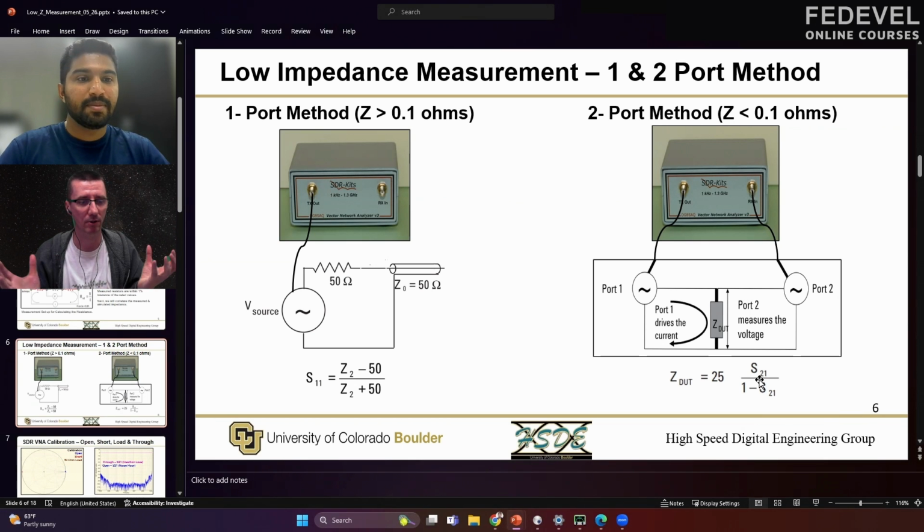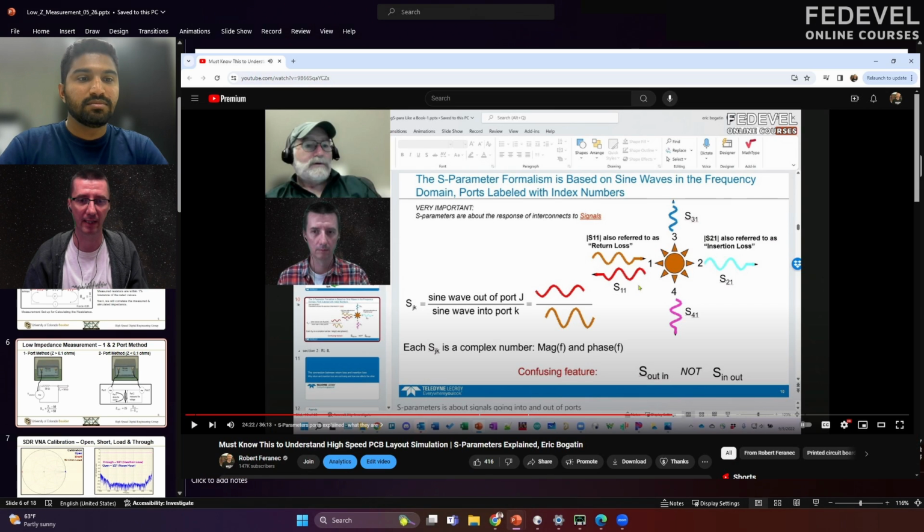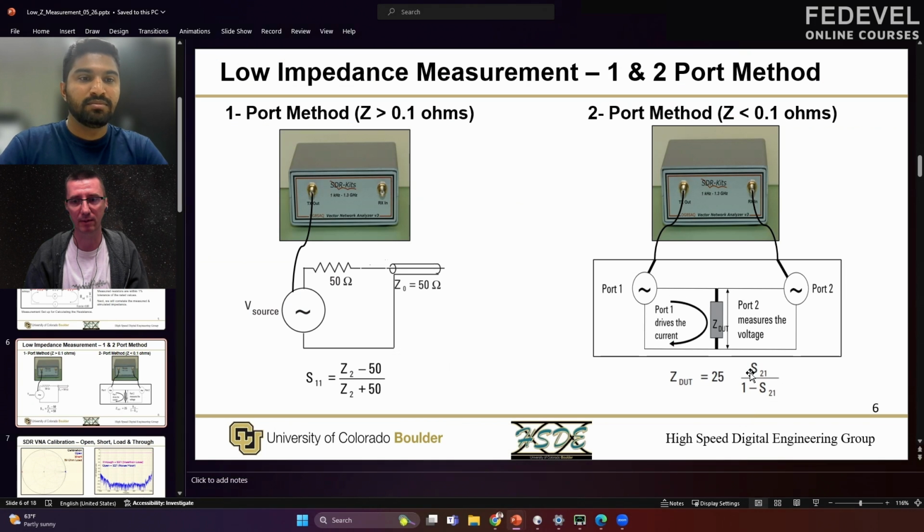For everyone who doesn't know exactly what we are talking about, basically what we did is we created a model of the physical connection, and then we can import this model. Normally, even for very complex simulations of your PCBs, you create these kinds of models. They are called S-parameter models, which can describe, for example, connections on your PCB, and then you can use these models in simulations.